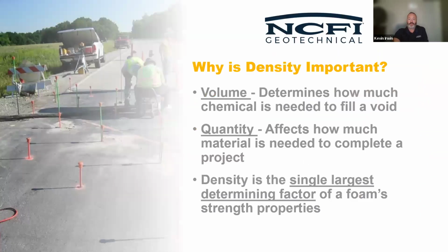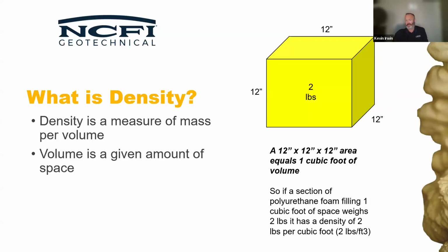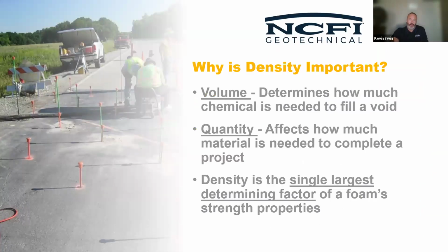But a 2-pound density, sorry, if I have 1 cubic foot of that system, it's going to weigh 2 pounds. That sounds straightforward, but we need to understand that that foam can pack, because it starts out as a liquid, and we're injecting it into the soil, and then it begins to react and expand, and now things change.